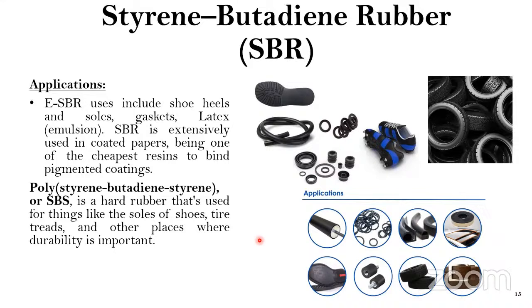That's why you cut it, because these soles are manufactured by using compression molding. You know that. We manufacture these soles using compression molding. So to feed the raw material into the compression molding, you should cut it into very small chunks, or you will have to use pellets or powder.